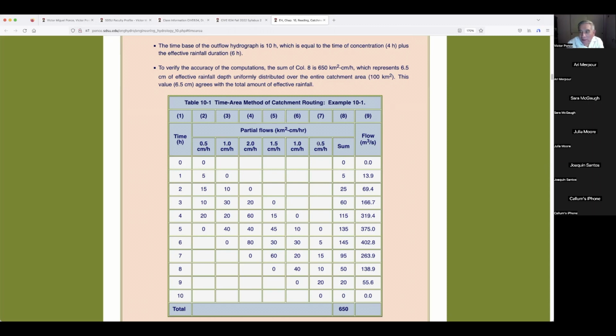There are also other methods out there, like the Philip, the Green-Ampt, and a couple of others that the Army Corps likes to use in their models, but they're also rarer. The curve number is prevailing, really. Okay, and we already talked about the curve number extensively. So once you apply the curve number in here, you separate the effective, and you get only effective rainfall.